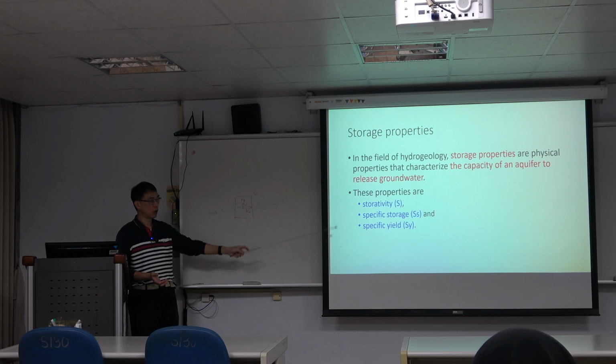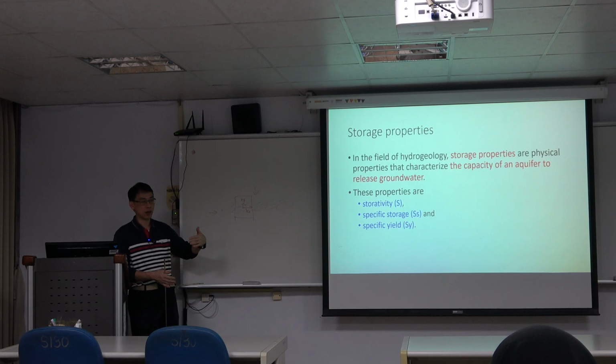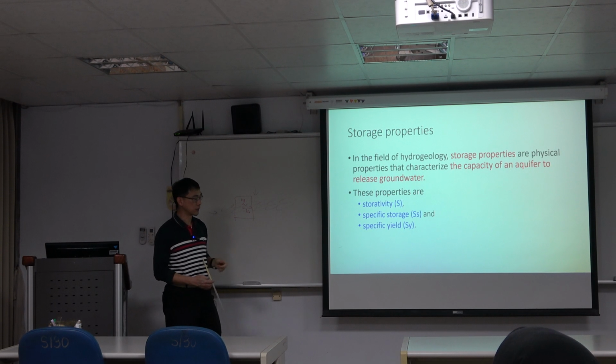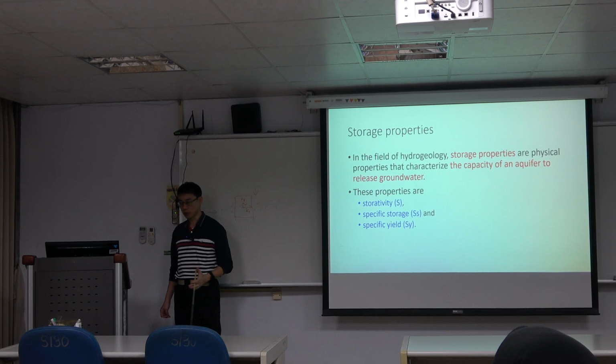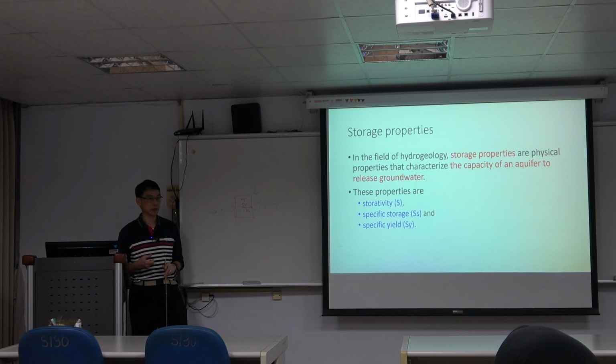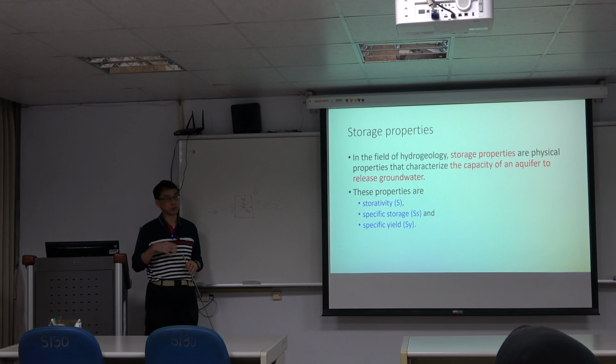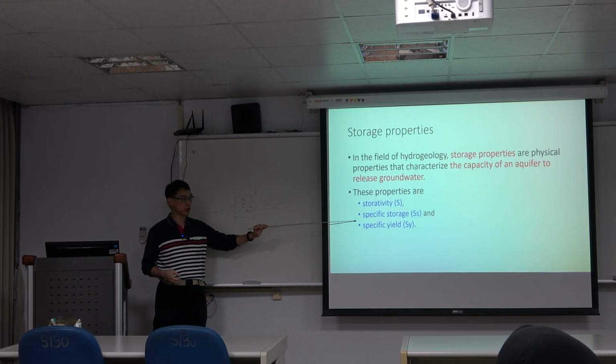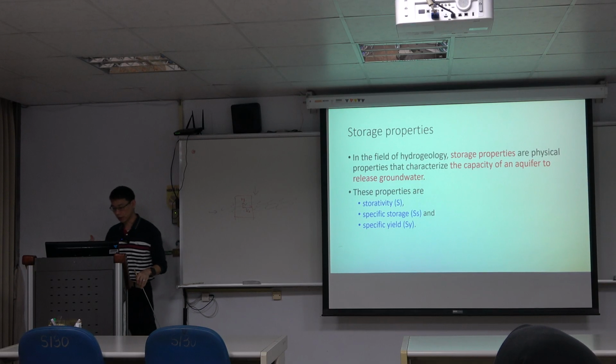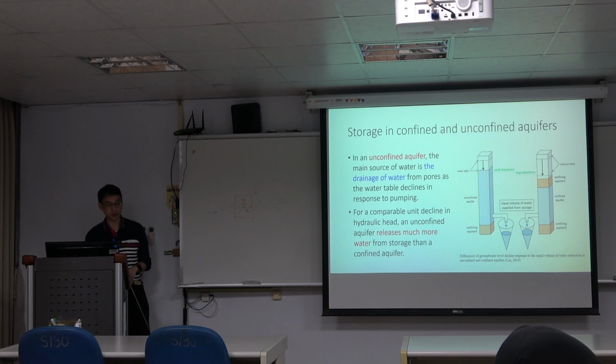All of the storage coefficients describe the same or a similar concept: how much water we can obtain from a unit change of the head. Although the definitions are a little different for these several parameters, because some use an average concept, and some, like specific storage as I mentioned, use the mechanical concept. They have the deformations inside, so they have a little differences.